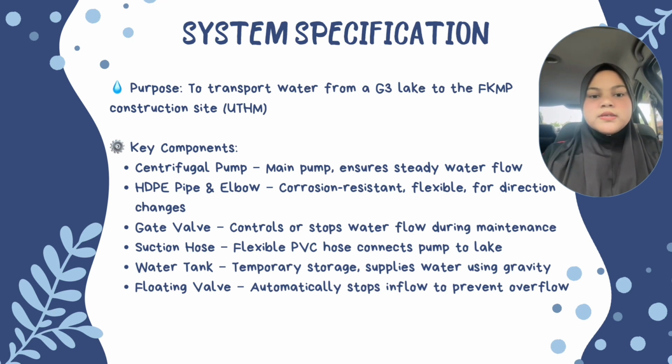The suction hose made from flexible PVC connects the pump directly to the lake, allowing smooth water intake into the system. Water is stored temporarily in the water tank, which is placed at an elevated position. This allows water to be distributed to the construction site using gravity without the need for additional pumping.